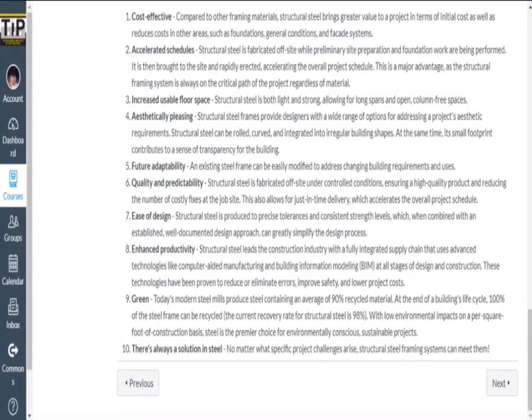At the same time, they can be light precisely because the sections for structural steel, especially in terms of cross-sectional area, are much less than that of concrete, because as we know, the strength of a structural member depends on both its section and material properties.